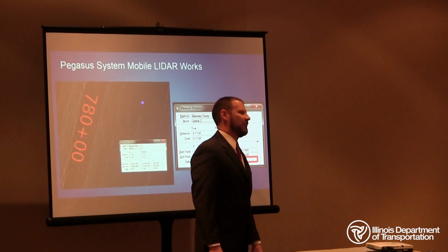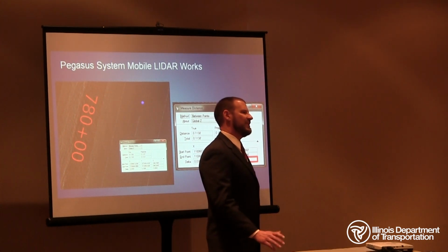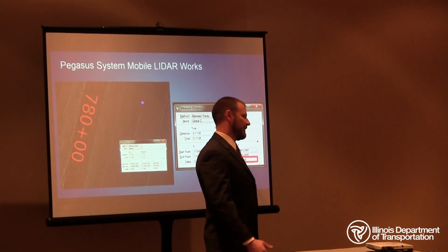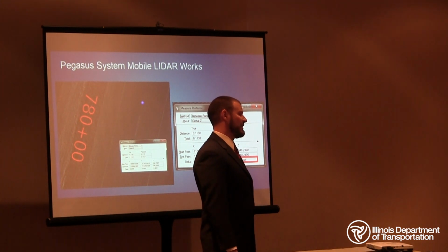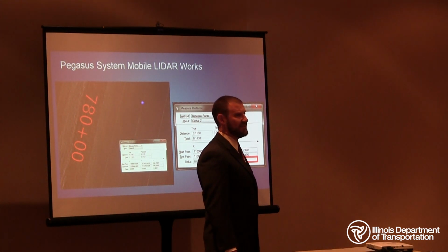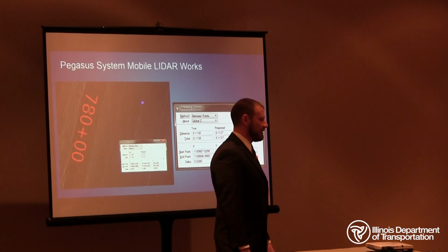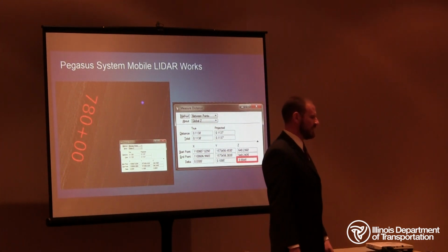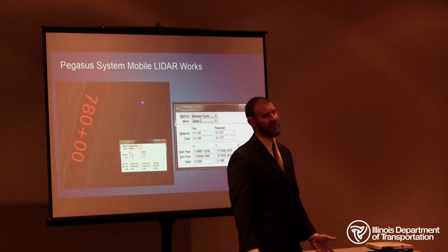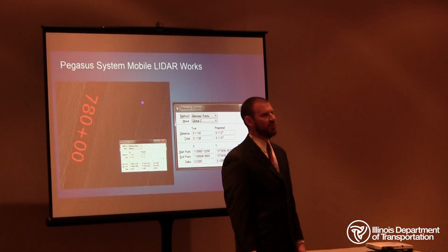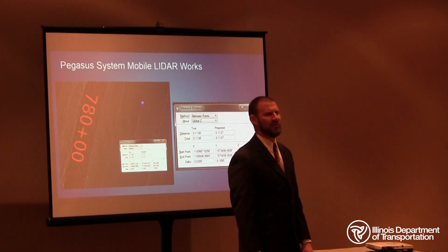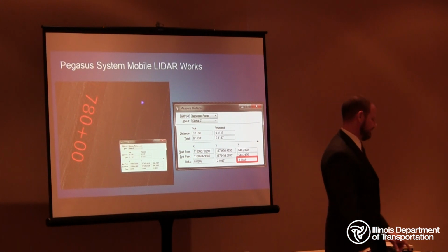So the data was shipped off to consultant C for them to readjust the point cloud. The point cloud came back, and I did a check of the conventional survey shot in that same location, and we closed within 0.0045, or less than 100th. For the type of work we do, you can consider that an immeasurable difference.